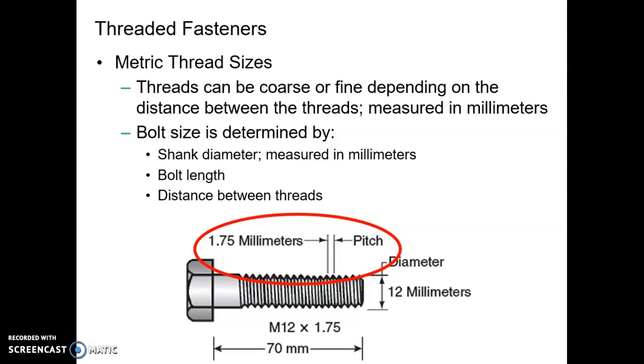Keep in mind, there are many SAE, USCS bolts and metric bolts that are very similar in size and will actually thread into holes. So if you're not careful, you may start an SAE USCS bolt into a metric hole or a metric bolt into a USCS SAE hole. Never force a bolt if it starts the first few turns and gets tight. Don't force it. You may have inserted the wrong bolt into the wrong hole. So keep that in mind. There are several types of bolts that are very close between the two systems.